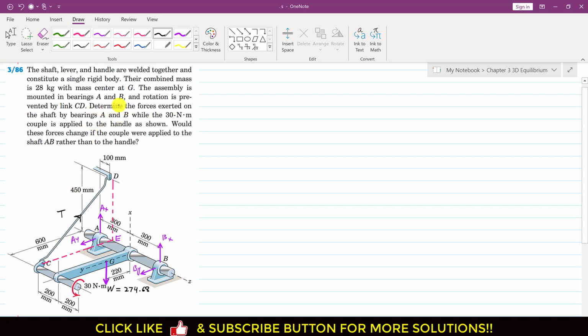So we are required to determine the forces exerted on the shaft by bearing AB while a 30 Newton meter couple is applied to the handle as shown, right? So we have a couple here, this is 30 Newton meter, and we are required to find these reactions, AX, AY, BX and BY reactions at this point A and B, and there is no reaction in the Z direction, right? Since the motion of the shaft is not restricted along this Z axis, right? So we will have two reactions at point A and point B respectively.